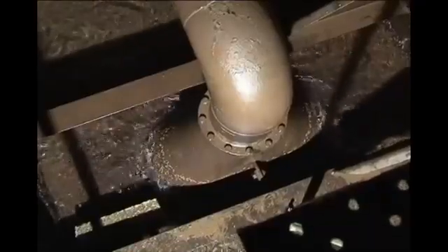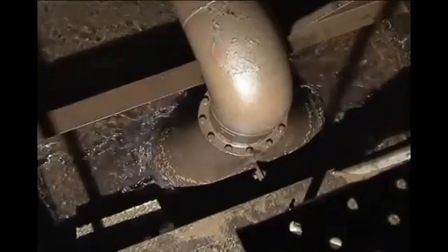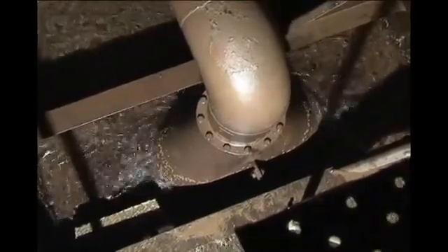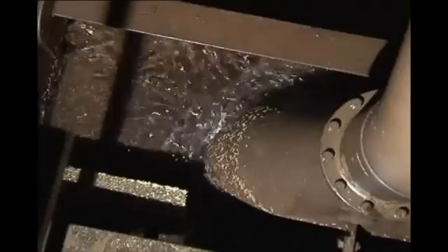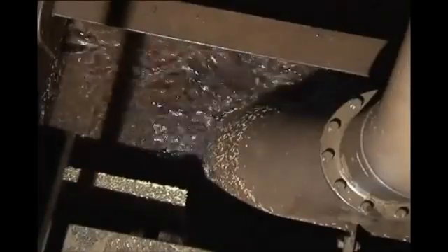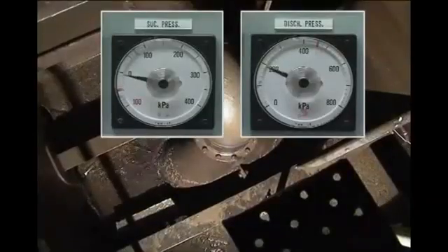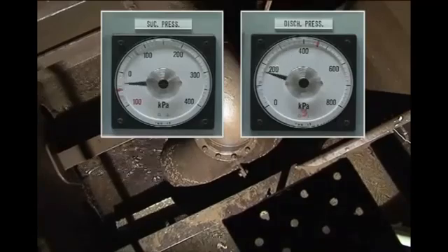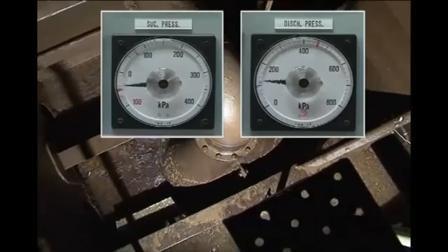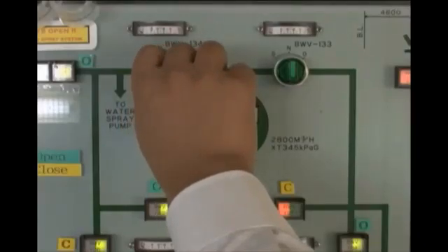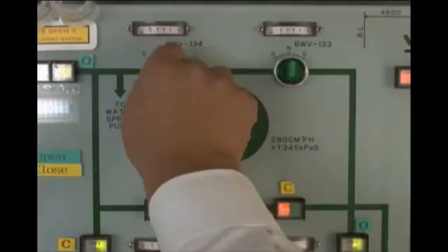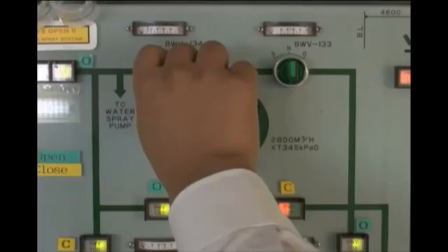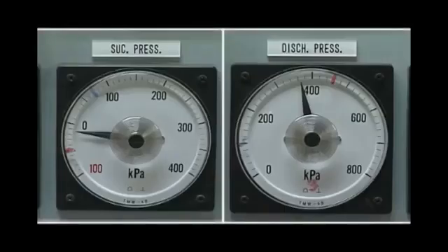As the water's surface level lowers further, the water rapidly whirls around the bell mouth while rolling. This makes it easy for the pump to draw in a large amount of air. At this time, the pump's pressure gauge reading becomes unstable. As a corrective measure, reduce the pump's discharge valve. Then the gauge resumes stability.